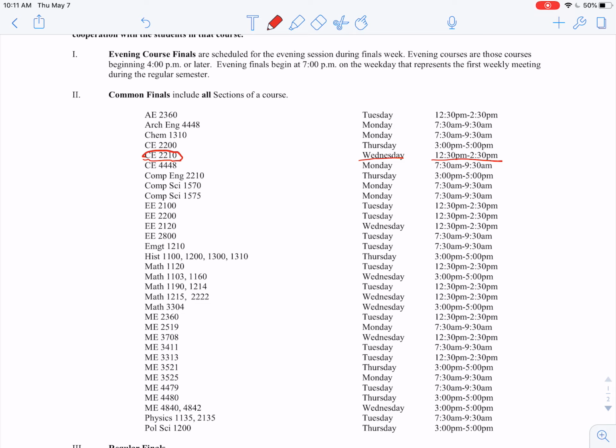For example, sometimes we have a hollow circular shaped cross section, right? So you will need to use the I to calculate something. How to calculate the I for this shape? If you have been familiar with the equations, you can easily write that this equals pi over 64 times (D to the fourth minus d to the fourth). This is the equation. But if you forget it, you need to know where to find it. It's not available on the formula sheet.